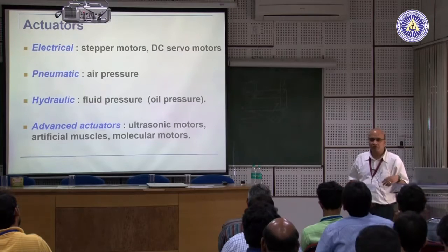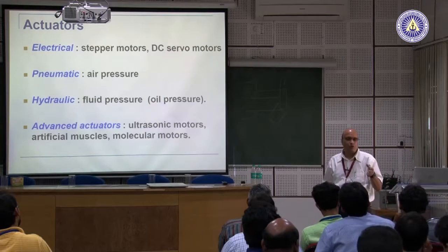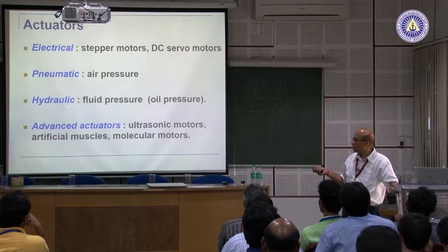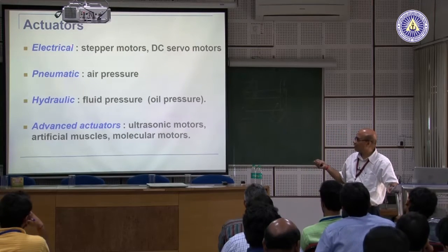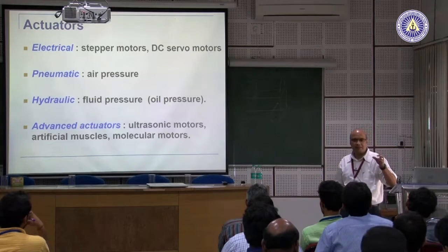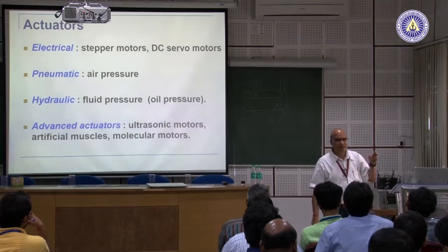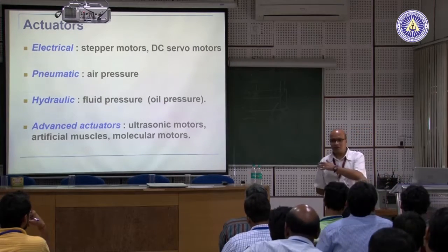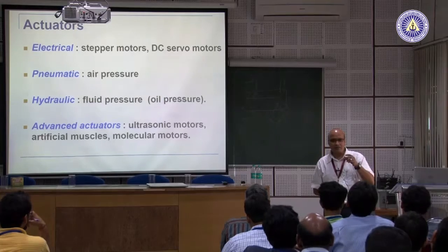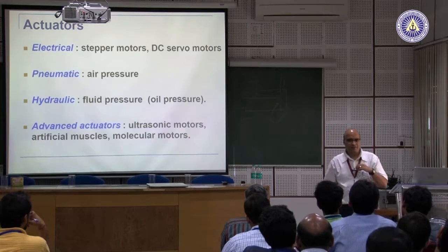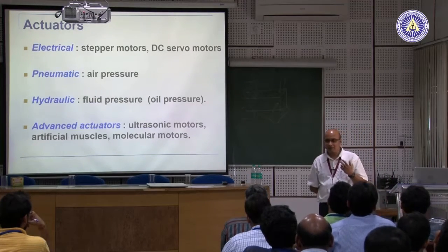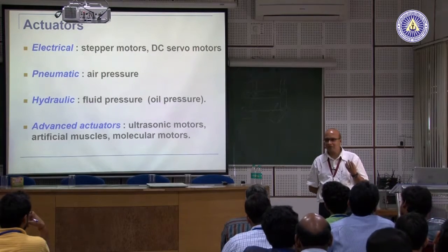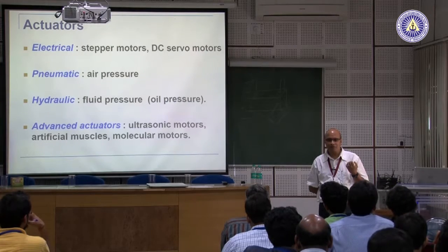Okay. So, robots which require very low power, they need to lift very low weights, we can go for electrical and pneumatic, we don't go hydraulic. So, 90% are electrical and pneumatic. Gripper is normally pneumatic. Why pneumatic? Why not electrical? Most of the robots you will see around, they have pneumatic grippers, even in the industries. Not electrical or hydraulic. Why pneumatic? Pneumatic has some advantages. What is the advantage? Faster response. Pneumatic is not faster, electrical is faster.